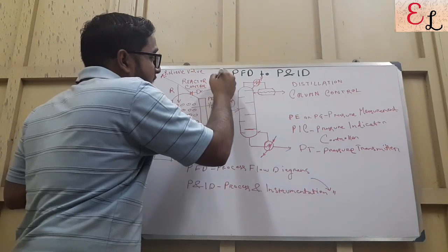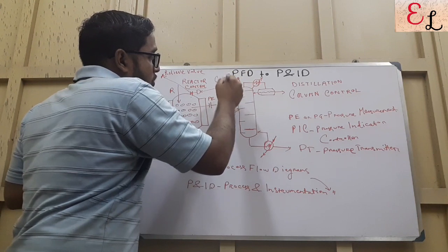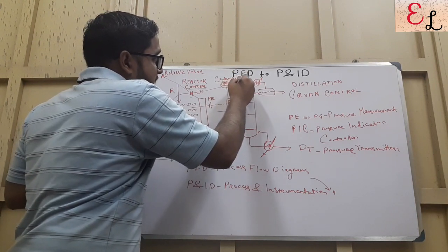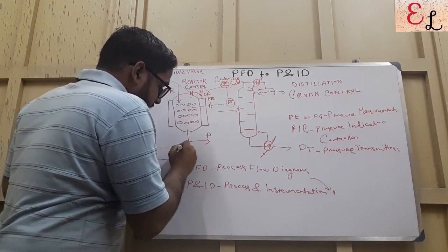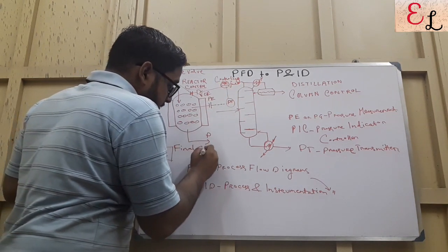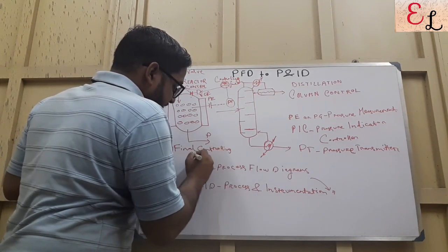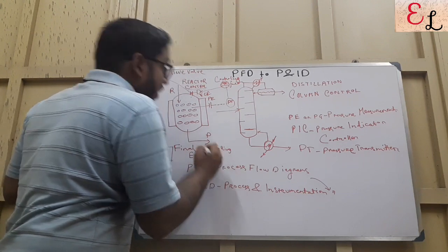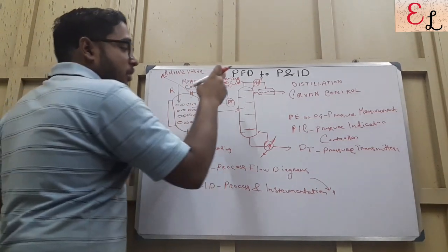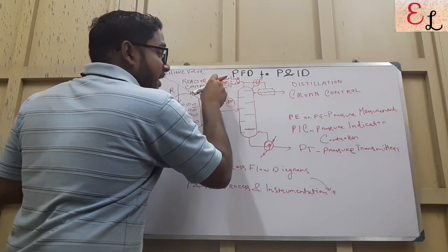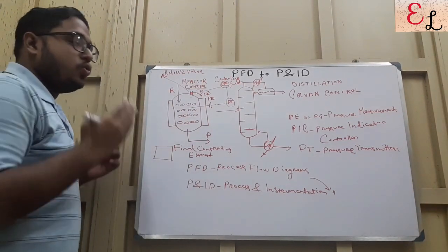So this is basically my controlling element, controlling factor, and this is my FCE, that is my final controlling element, or actuator, also known as the actuator. So basically, first to measure the pressure, then to transmit, and then to indicate and control it through a valve system. So you need to find ways to do this.